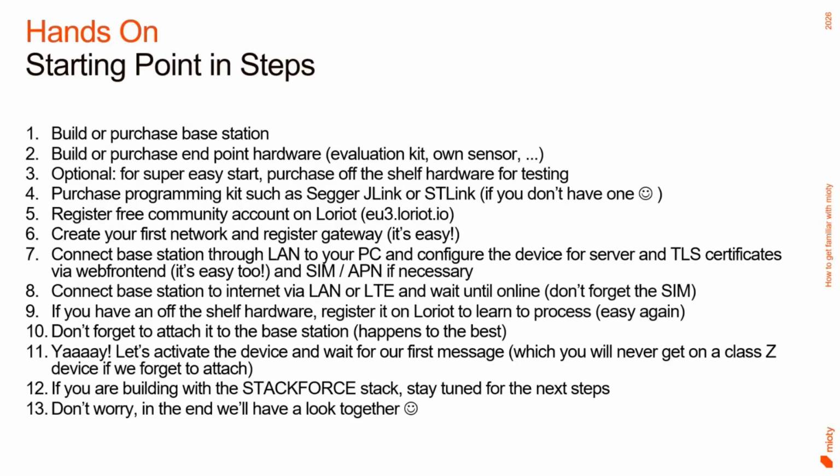Then, of course, you need some endpoint hardware. You can get your own sensor. You can use an evaluation kit. You can also literally use just an STM32 Nucleo kit. So that's really up to you. I would really recommend, if it's your first time with mioty, to get some off-the-shelf hardware. You can get it also from Lansen, Deal Metering, Sentinum, so that you can verify your setup before you start fiddling around with your own solution or your own device.